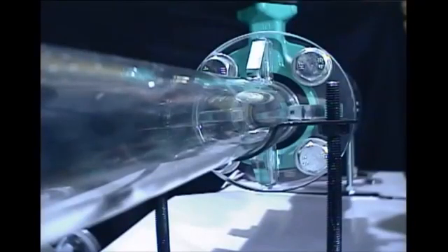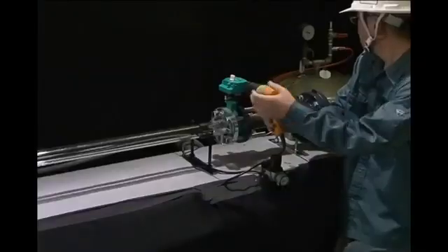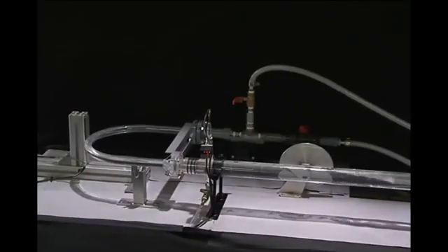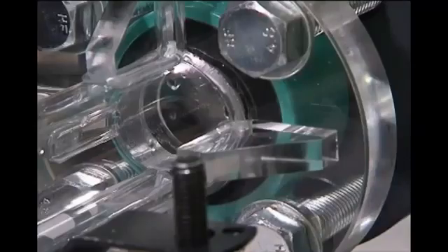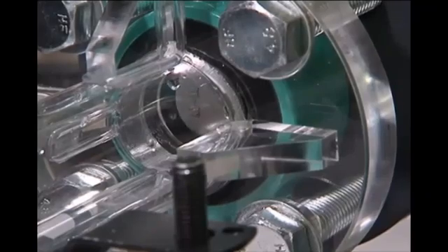The section of the acrylic pipe from the valve beyond is of negative internal pressure. In actual ballast operations, there are cases where cleaning with an eductor is carried out in the final stage, which calls for the ballast line pressure to be negative. This equipment simulates such a condition prone to accidents. First, let's look at a case in which the butterfly valve is fully opened suddenly.